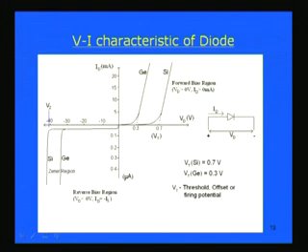It is called Zener breakdown because this phenomenon is utilized effectively in the Zener diode, which we will be discussing later. That is why this is also known as Zener breakdown. For a Zener diode, this breakdown can occur at a smaller voltage, because a Zener diode is a special kind of diode that we will discuss later. It is a very highly doped diode. When you dope it very highly, the breakdown voltage will be smaller. If it is lightly doped, you will find that the breakdown happens at a greater voltage.